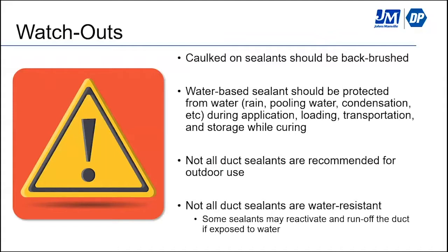Especially with water-based duct sealants, make sure it's protected from water while it's curing. Rain, condensation, transporting on stake body trucks can all cause the water-based duct sealer to wash off before it's cured. Also be aware that not all duct sealers are recommended for outdoor use. There are a lot of duct sealants out there that are not water resistant, meaning after they are cured, they can run off the duct. If it gets wet, they can reactivate.